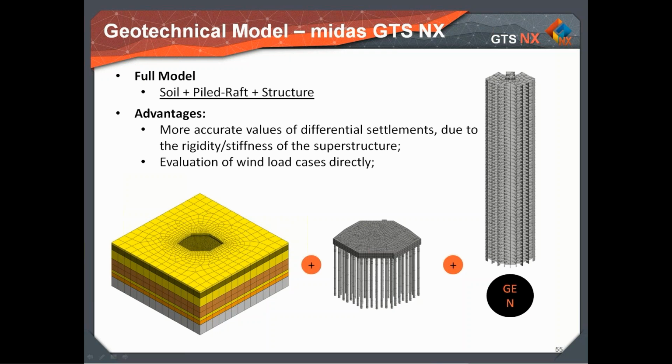Looking at our model, if we create a full model, which is the soil plus the Piled-Raft plus the structure, as was said, it is understood that the differential settlement behavior seems to be closer than when using other kinds of models. Another advantage is being able to evaluate different load cases directly, and also wind load.